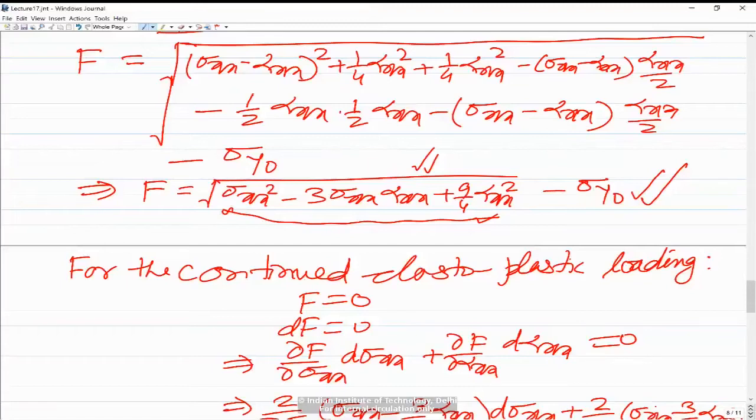Initially we start with an initial guess of the displacement vector, the degrees of freedom, as a zero null vector. Once the solution converges for one load step, then for the next load step we take the converged solution of the previous step as the starting guess, and that is how we proceed.